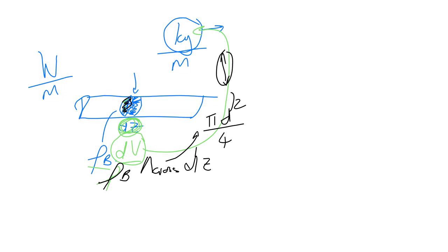So this will give me the mass of catalyst, but what I want is the mass of catalyst per bed length. Fantastic, look, that cancels out. The factor that I actually need is just the bed density times the cross-sectional area.